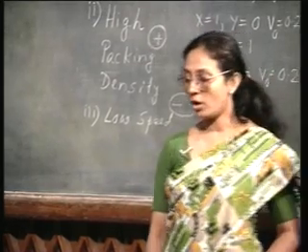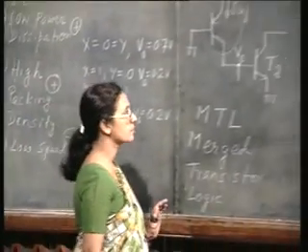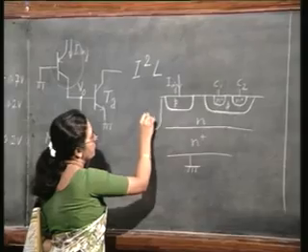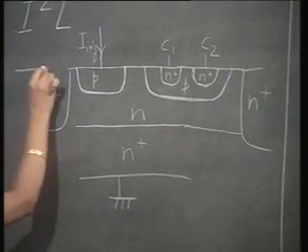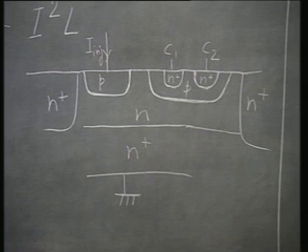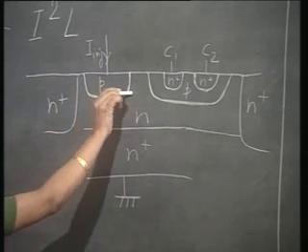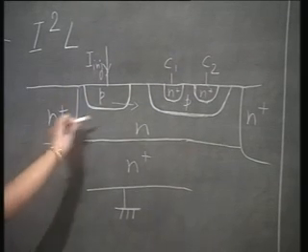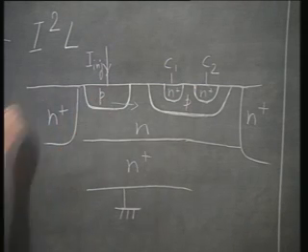But of course, in order to make the circuit perform in a more efficient manner, you can use two N plus regions called the N plus collars on both sides of the P diffusion. Okay. This is simply done in order to facilitate hole injection. You see, you are injecting current. You want the hole injection in this direction, P and P. However, as far as holes are concerned, they do not see any difference between this direction or this direction.